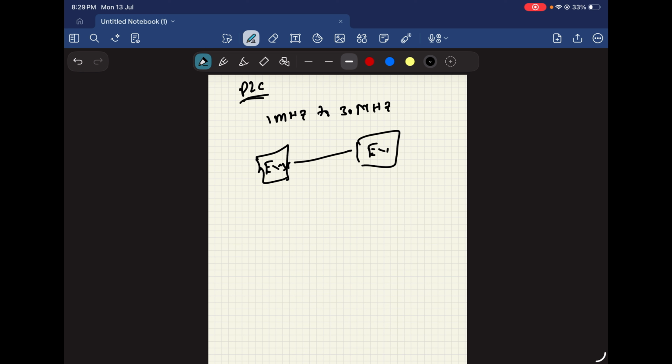PLC means bidirectional communication, as per the standards for smart grid and DC fast charging stations, where bidirectional communication is required. Normally PWM communication means only one-way communication. There is no data transfer between these two, EVSE and EV.